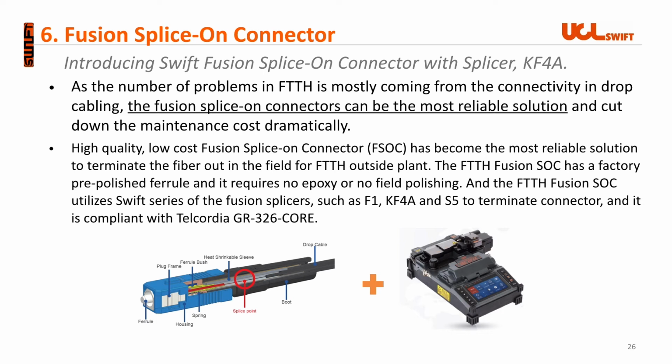The FTTH Fusion SoC has a factory pre-polished ferrule, and it requires no epoxy and no field polishing. The FTTH Fusion SoC utilizes the Swift series of fusion splicers, such as the KF4, to terminate the connector, and it is compliant with Telcordia GR-326-CORE.